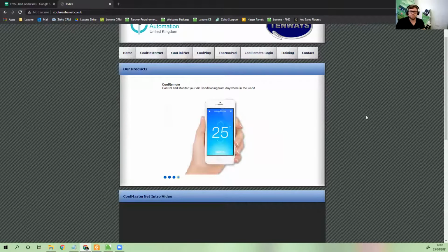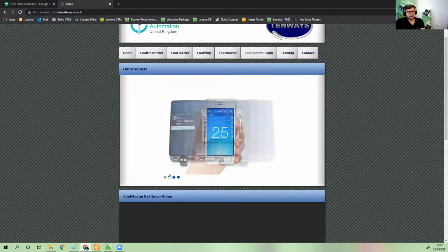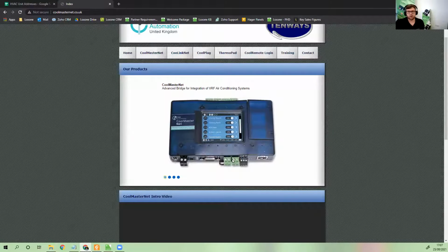We'll use Modbus IP. Now, the other cool thing is, even though that's 7 lines for up to 7 different aircon units, if you wire that line to, say, an outdoor unit, you can control every indoor unit connected to that outdoor unit. I believe up to 64 indoor units per outdoor unit. So in this office that I am sat in, we have in total, I think, 22 indoor units across the entire office spread across 2 floors. And we can communicate with all of them through 2 connections from that Coolmaster unit. So that's really cool. No pun intended.